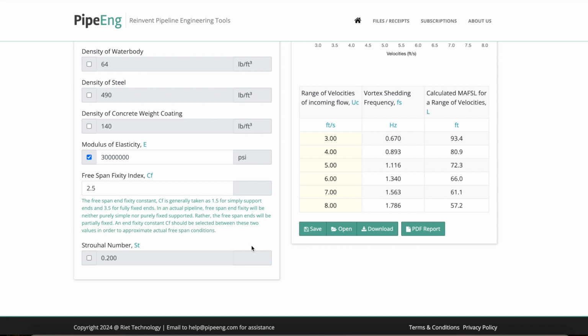There's a pipe-soil interaction we have to consider. Even a virtual anchor can be quite a bit of distance away, because the virtual anchor is defined as where the pipe-soil friction is big enough to act as an anchor point to offset the thermal expansion and all that.